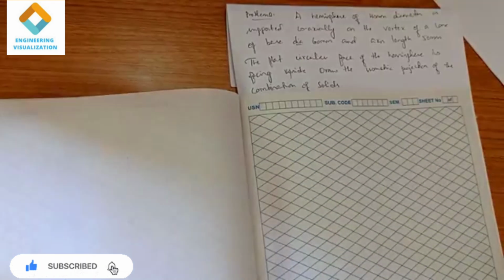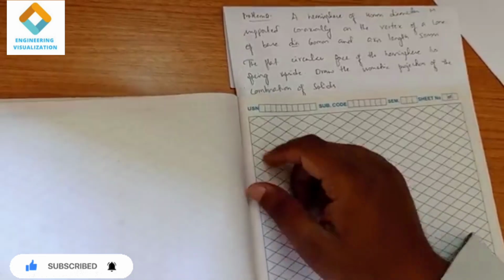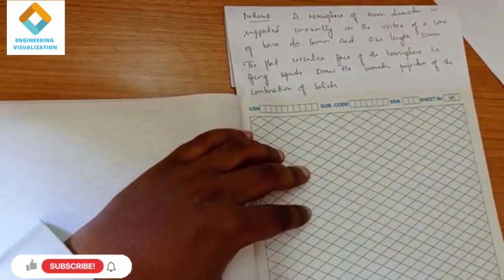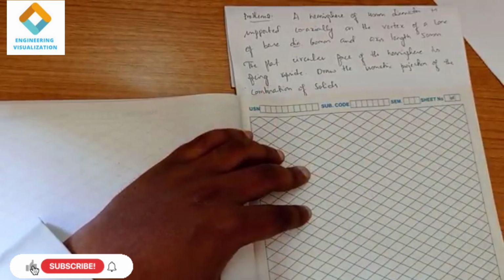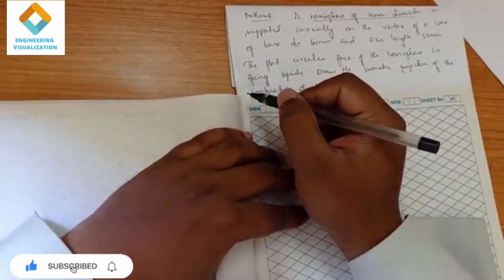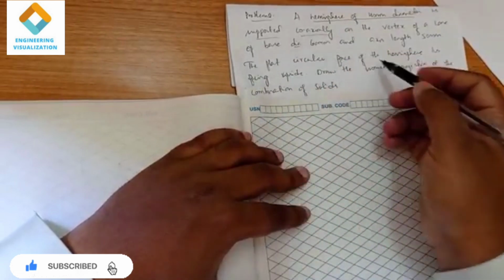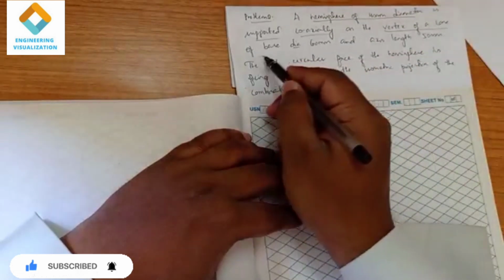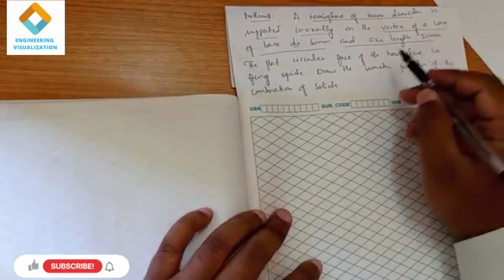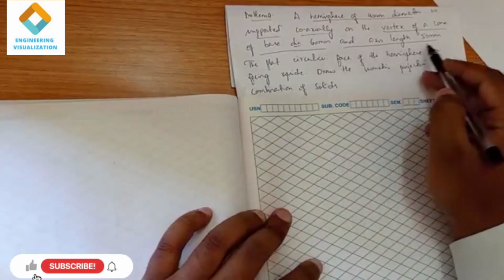Now the second problem in isometric projection. You can see the question here: two solids are given. One is a hemisphere of 40 mm diameter. A hemisphere is nothing but half of a sphere, supported coaxially on the vertex of a cone. The second solid given is a cone. For that cone they have given a base diameter of 60 and an axis length of 50.